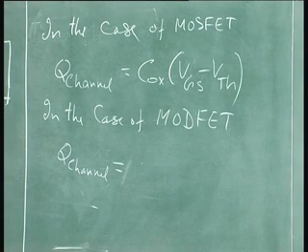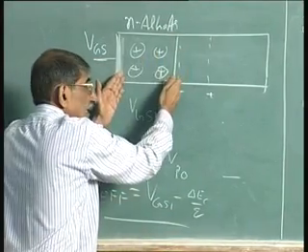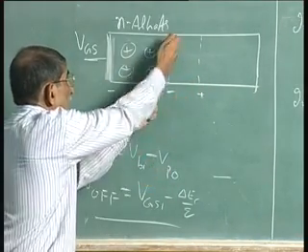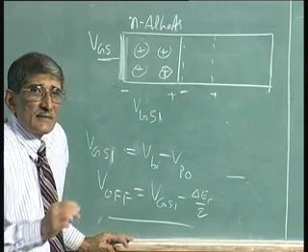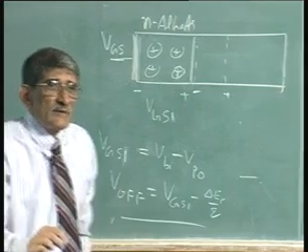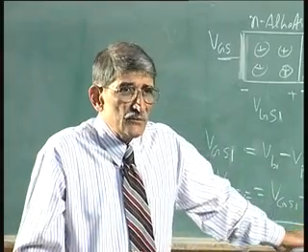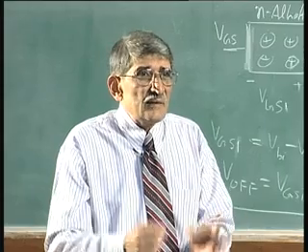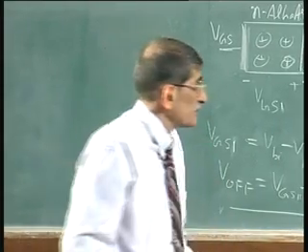See, in the case of MOSFET you have metal, oxide, semiconductor. In this case you have got metal, aluminum gallium arsenide which is fully depleted, and the semiconductor. It is inversion, you have got the notch charge. So, coupling is between these two. Why I am bringing this analogy is that it is exactly the same as MOSFET hereafter. All that you have to know is, if I apply voltage V off equal to VBI minus VP0 minus delta EC by Q, that is the threshold voltage, you will turn off the channel. Whatever extra voltage you apply above that will couple between the gate and the channel. That is all you have to see.